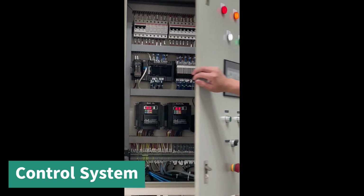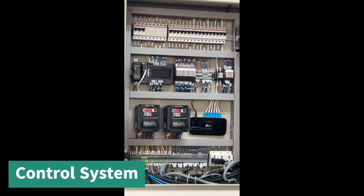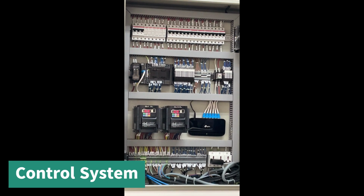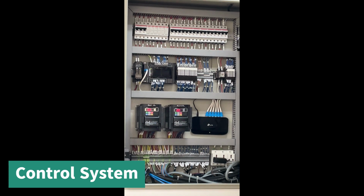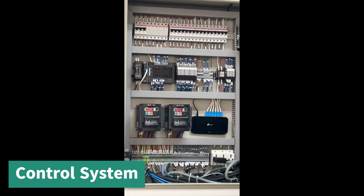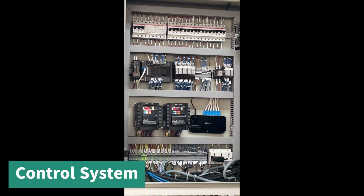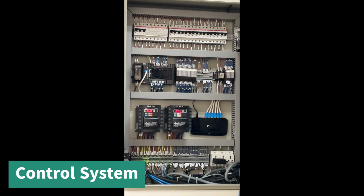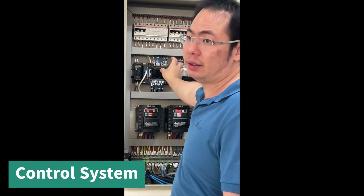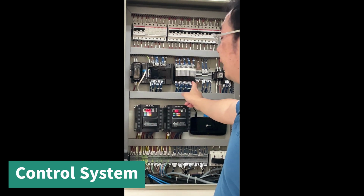Control cabinet. Located on the right side of the image, it includes status lights, e.g., green, red, and a touch screen, HMI, for setting parameters or controlling processes. The control cabinet connects to the robot and conveyor belt via industrial communication protocols such as Modbus or EtherCAT. Control software processes data such as image recognition, position calculation, and sends commands to the robot's motors.